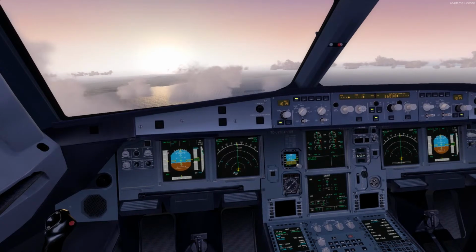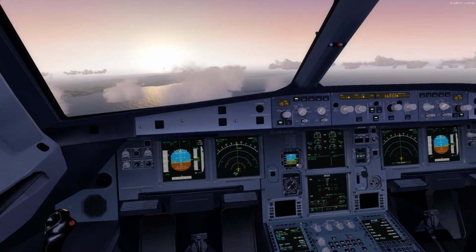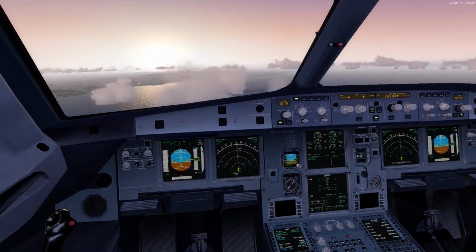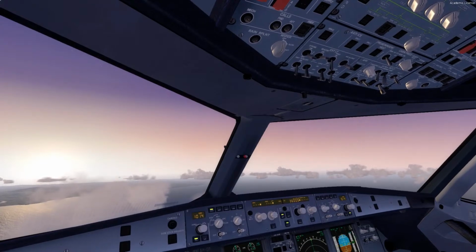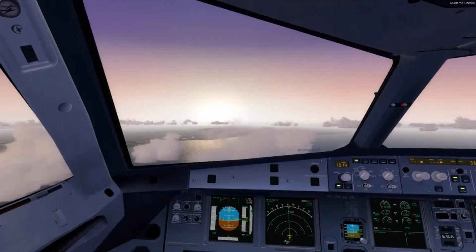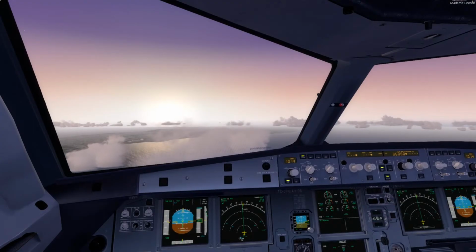As I checked the arrival, we can also anticipate that we'll get the radar vectors at Ljubljana, but we have planned the Magam 1 Romeo arrival for now, as we don't know which arrival we'll get. We'll continue now, climbing from flight level 110 further, and we can turn off the landing lights and the wing lights. We can also turn off the seatbelt signs for now, and we're further climbing inbound to Aden,